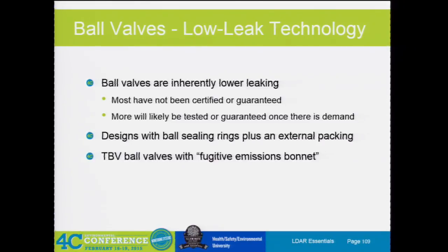So if you had one that leaked and you had to replace it per a new consent decree or something, you just say it's a commercially unavailable product. You have to be sure that you reach out to the different vendors to basically show that it is unavailable. And then with the low E and with all, there's tracking requirements with it. So you're going to have to make sure that you have all the certifications for any of the low E. And you have to have a written guarantee that says they will not emit above 100 ppm for 5 years.